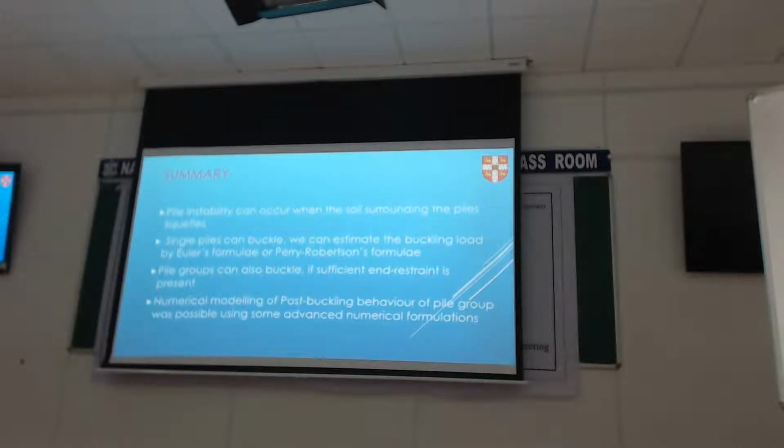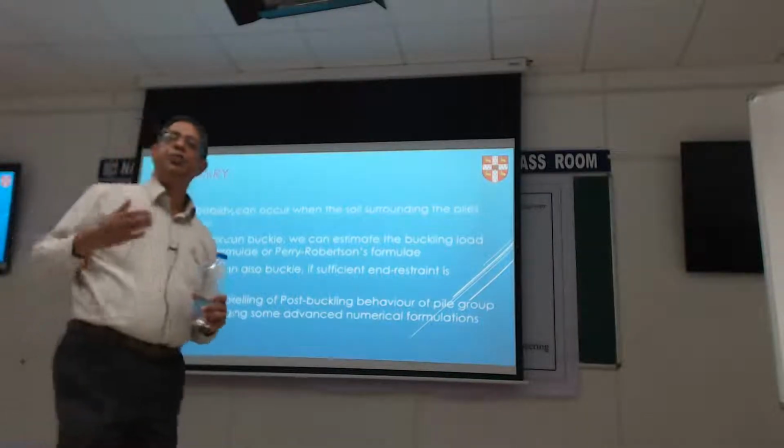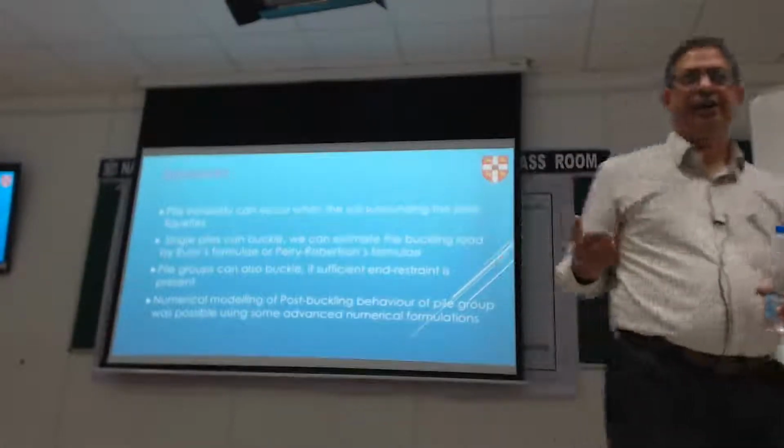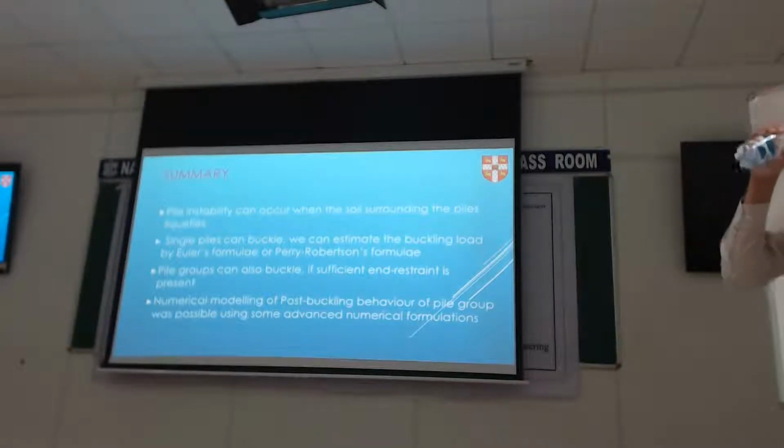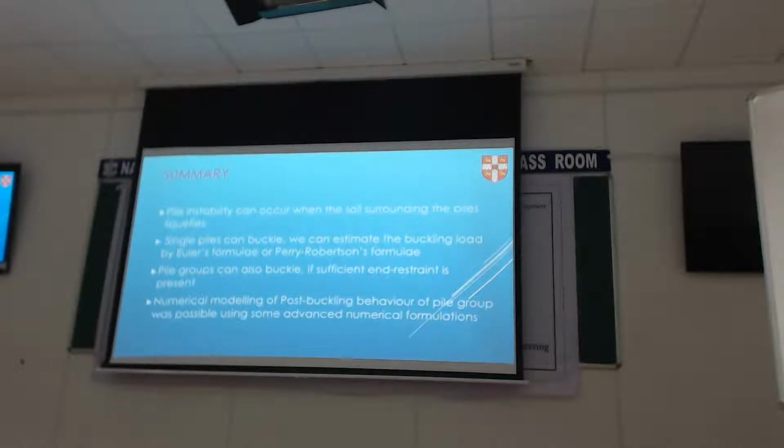It is possible, if you're more research-minded, to track the pile buckling in the post-buckling period because, A, it could be fun, and B, if you're doing ultimate limit state (ULS) calculations, you want to know how far you can push your piles. If you're doing that, this is quite a good way of making progress. So there are lessons there for simple engineering calculations as well as for some sophistication if you want to.